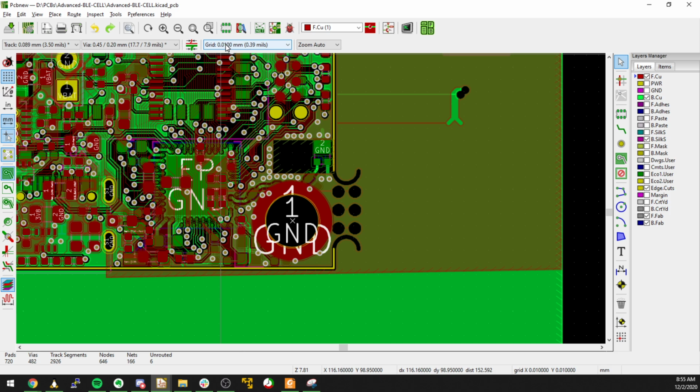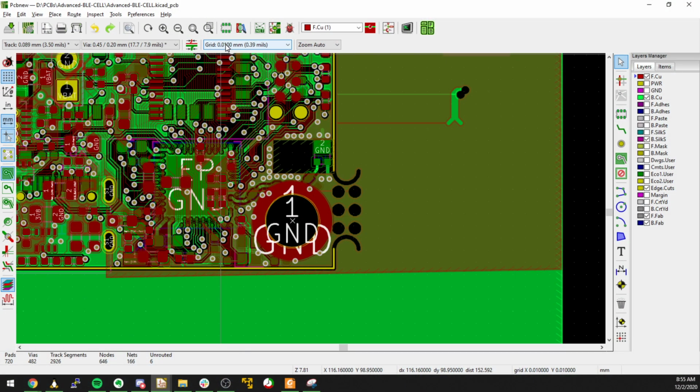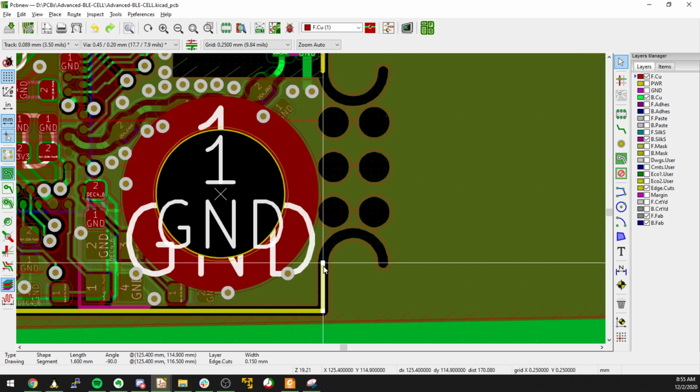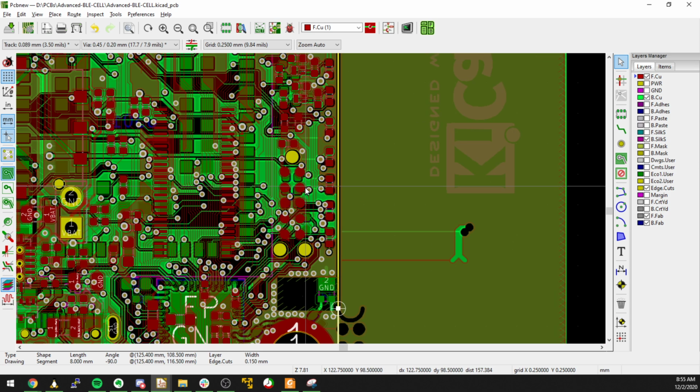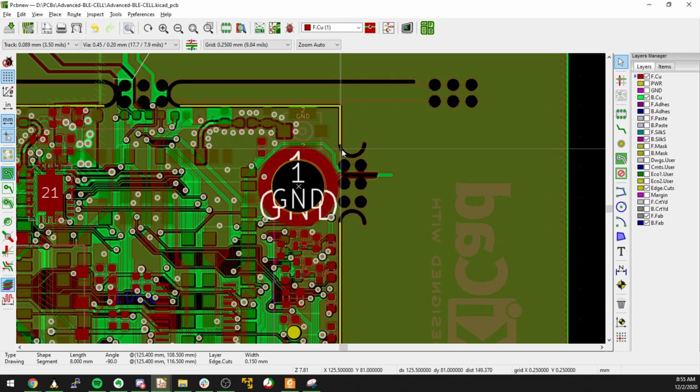If you hit N, it will downgrade, and Shift N will then upgrade it. That's a hotkey I've been using on purpose. Usually I hit it by accident in the past, and if I hit Shift N, you see that the grid underneath my mouse is going back up again. That's nice just for making it a little easier to drag stuff around. Hopefully this is on the correct spacing already, so it's easier to actually connect these things.